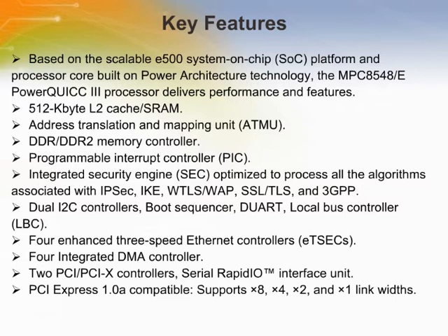Key features include a 256 KB L2 cache, integrated security, 64-bit DDR 1 and 2 scaling up to 400 MHz data rate, 32-bit PCI, 4-bit serial rapid I/O or 4-bit PCI Express, and 2 GB Ethernet interfaces. With clock frequencies scaling from 800 MHz to 1 GHz, this cost-effective device is ideally suited for a wide range of general-purpose embedded control applications such as robotics, discrete manufacturing, and process manufacturing control.